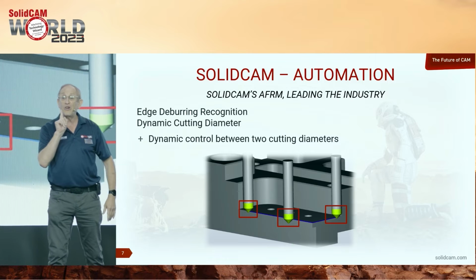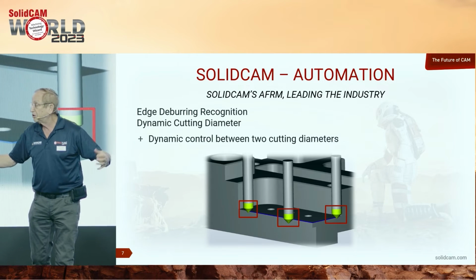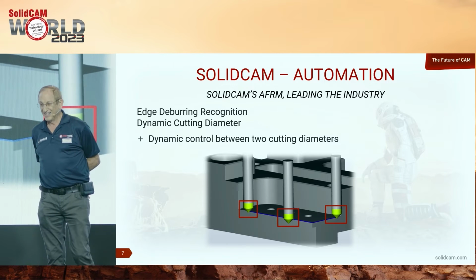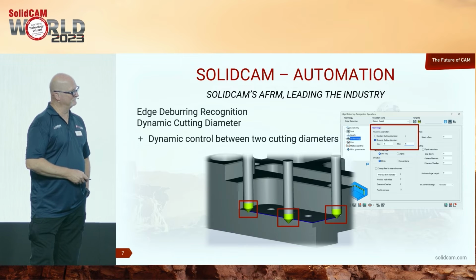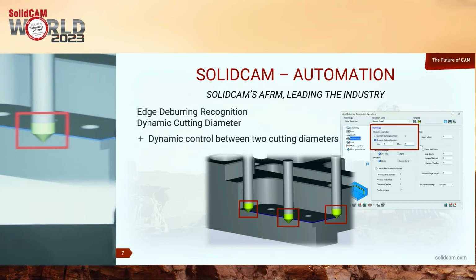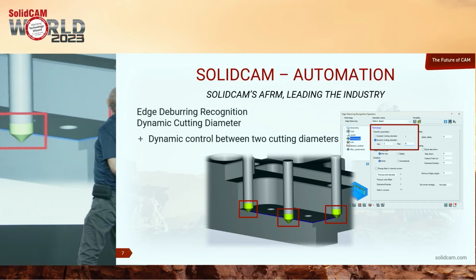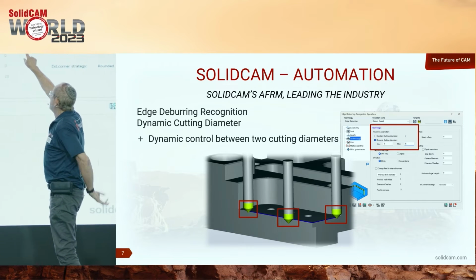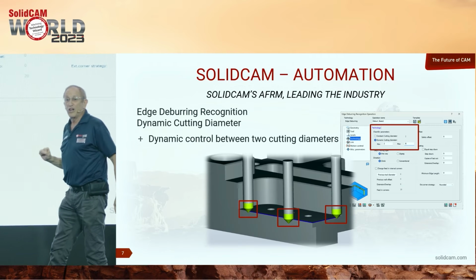This is very, very important for hard materials and also when you have large parts. It won't create a notch in your tool. And this does it dynamically, which is why the name is there, right? So here's where you set it. Exactly. Inside our technology field, we've always had the option, as you see over there, of the constant cutting diameter, but we've now added the dynamic cutting diameter.